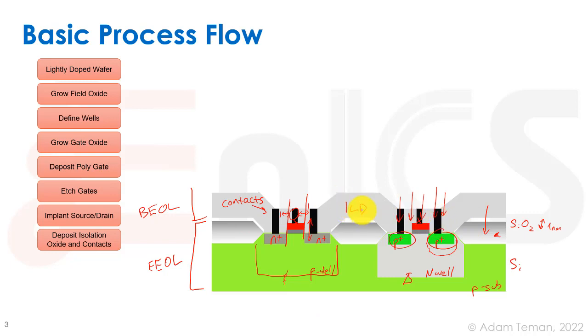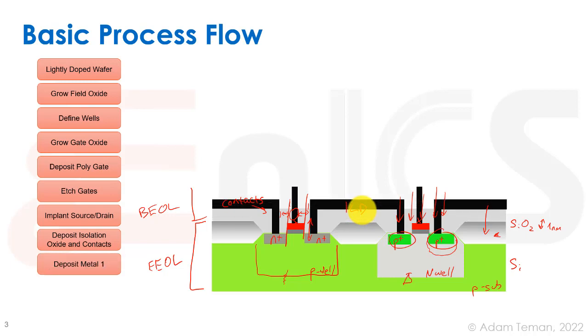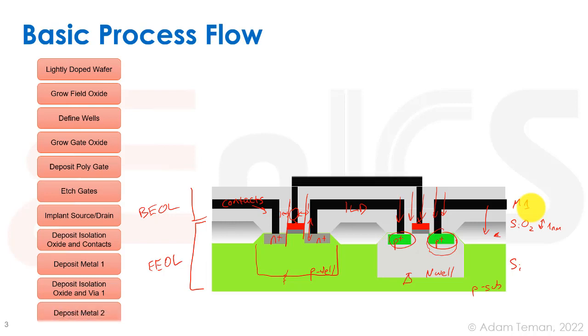Okay, so that would be our contact layer, and then we're going to polish away the interlayer dielectric and make our next metal layer on top, which is going to be our metal 1 layer. And we can pattern that, and then again grow some interlayer dielectric around that to isolate between the different metals, and put another metal on top, and this would be our metal 2 layer. And voila, we get our CMOS inverter with this kind of funny cross section over here.